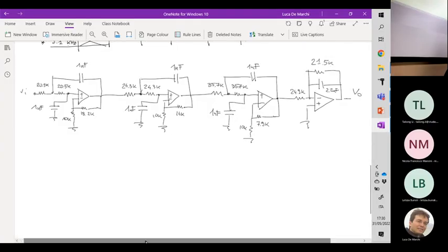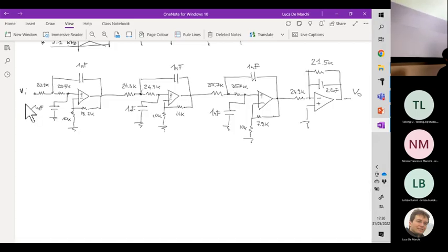The lazy strategy has, however, some limitations when we consider the sensitivity to parameter variations. So one possible alternative is to switch to the strategy for the Sallen-Key implementation that we have called SMART. We are going to implement the same exact topology, but with different parameter selection in order to minimize the sensitivity to parameter variations.